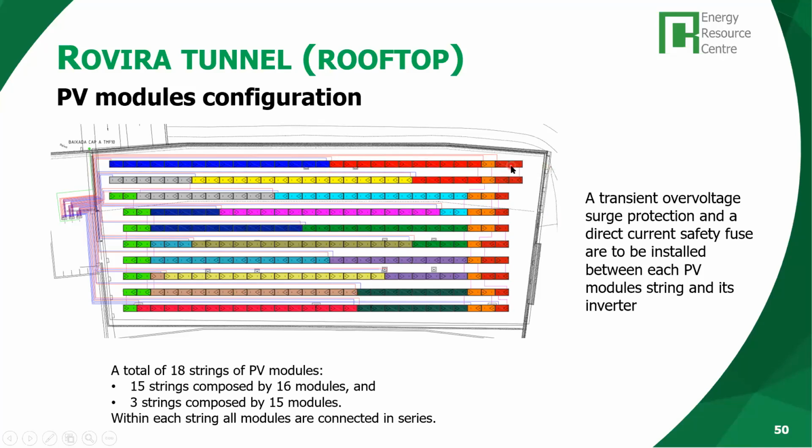And when you have in the inverters, like I said before, this range of input voltage from the strings, this is a large range, maybe 300 volts to 700 volts. And it's good that the output voltage of the strings is in the middle of this range, maybe 500 volts in DC.